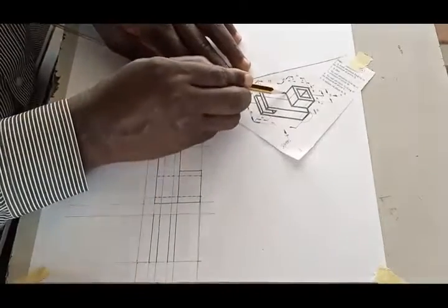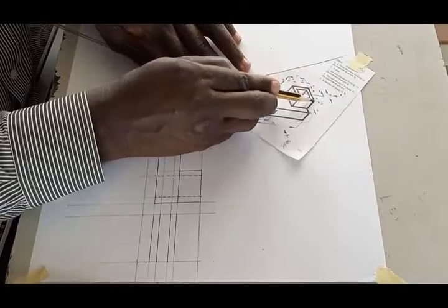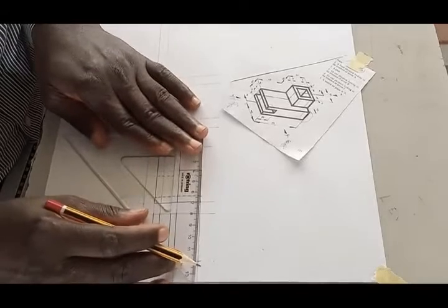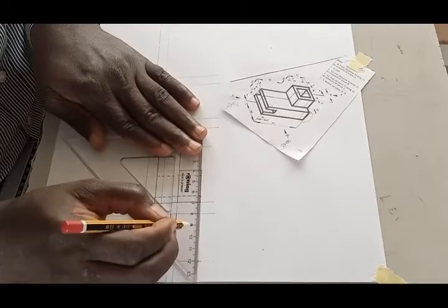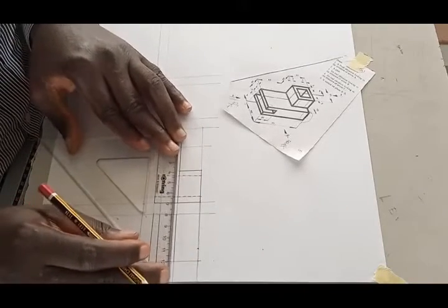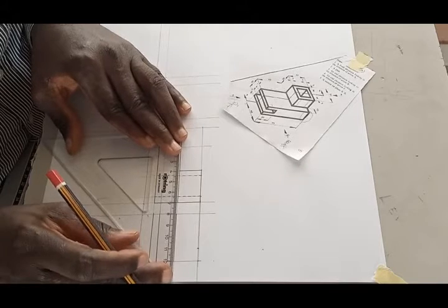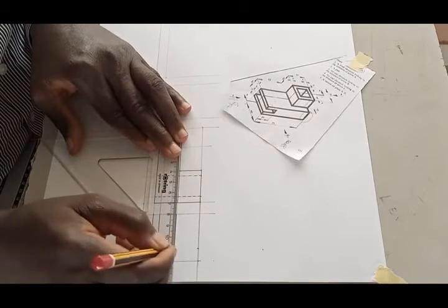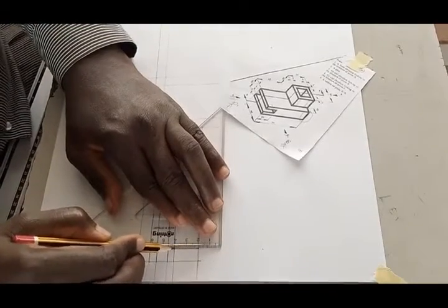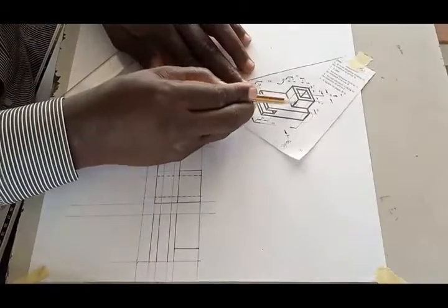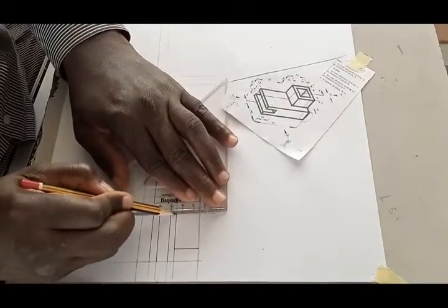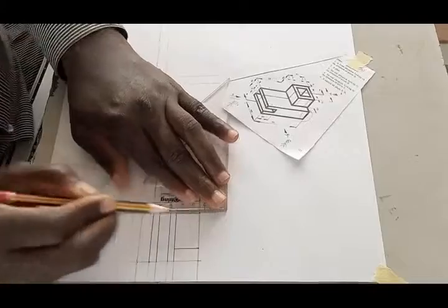And the width here to here is 30. You can see it here to here is 30. So from the left you measure 30. 1, 2, 3. That is 30. You can just do the same thing here, or you can use your t-square and set-square to transfer it. 1, 2, 3. So you have this like this, and it will be thick line because the outline that is here, and this other edge too will be thick line. This other edge will be thick line up to this portion.